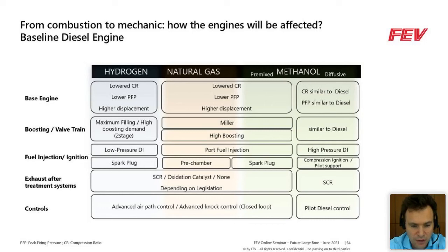Then, at the end, exhaust aftertreatment and controls will depend strongly on local legislation. Especially for hydrogen, we have quite high hopes that non-SCR solutions will also be possible. But nevertheless, for the strictest or close-to-zero emissions, especially considering transients, most likely an SCR will be needed, as well as for diffusive combustion. For sure, an SCR will be a topic, and I will show you some more detail later. There is also a very strong discussion regarding particulate number, and most likely in the future this will also be limited, and we have to consider some particulate filter.